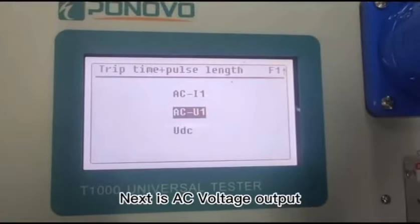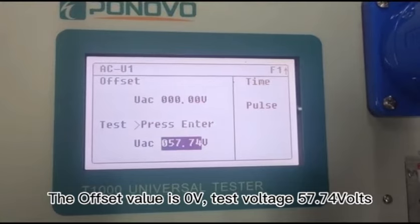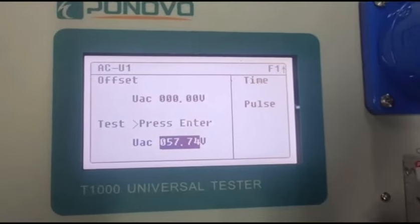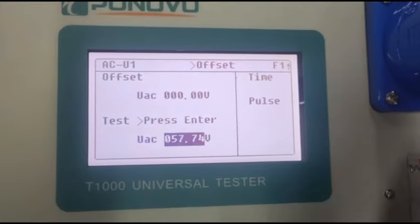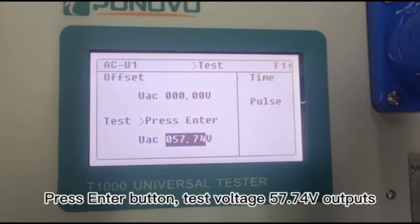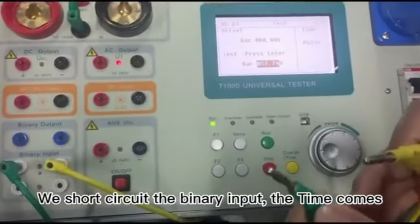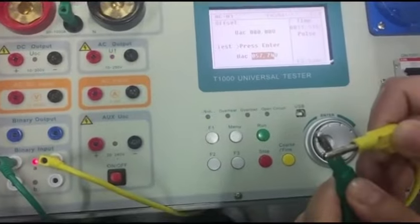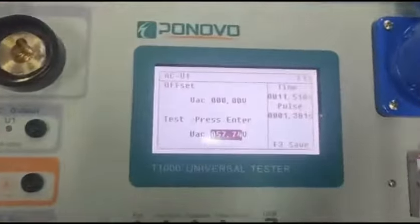Next is AC voltage output. The offset value is 0 volt. The test voltage 57.74 volts. Press Run button, offset value is output. Press Enter button, test voltage 57.74 volts outputs. We short circuit the binary input, the time comes. Open the binary input, the pulse time comes.